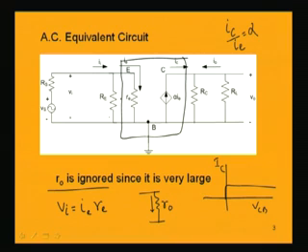But in any way we write, ultimately we will be getting the same expression, because what is IE in terms of Ii? IE is nothing but Ii into capital Re by capital Re plus small re. So, this is the I current multiplied by small re. Even if you take this other resistance and find out the current, it will be Ii into small re by Re plus small re into capital Re.